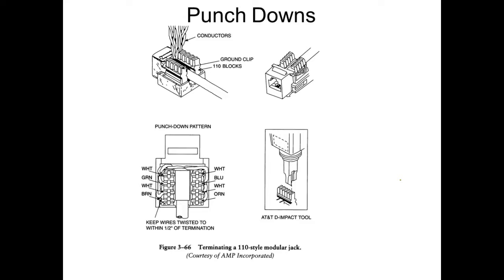It's only when you hook two DTEs together, and you can understand you do that. Like when I need to program that PLC over there. Well, if I want to program that PLC, I want to take my computer and hook it up to the PLC, right? You understand? So I got to have a what? So a PLC considers itself to be a what? A DTE. A computer considers itself to be a DTE. So I have to use a crossover cable for a PLC. So that's why we got all these crossover cables, so we can hook up our PLC.